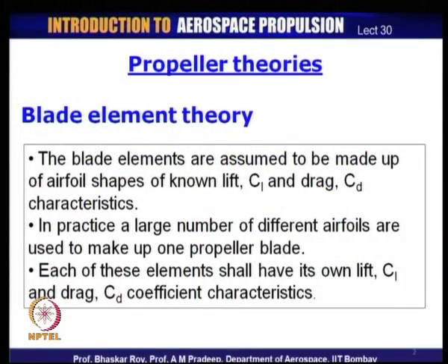So, let us take a look at the propeller theory that uses the propeller blade shape as it actually is, and the aerofoil sections, which actually provide the conversion of lift and drag to thrust and matching of the torque that is provided by the engine. The theory that uses the propeller blade shape is simply known as blade element theory.